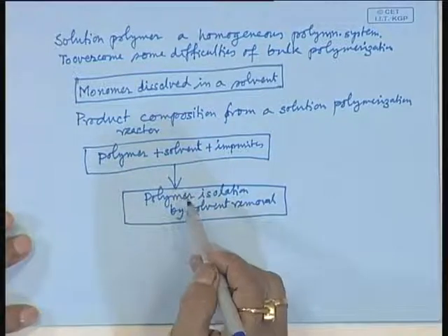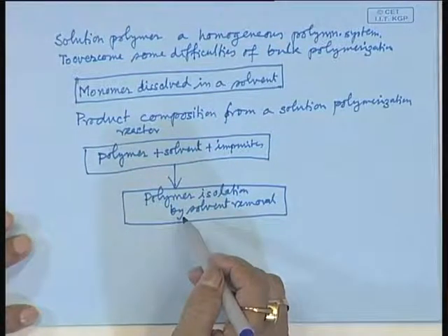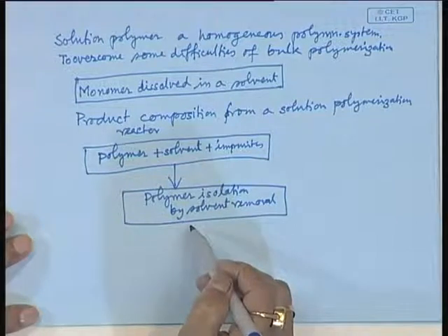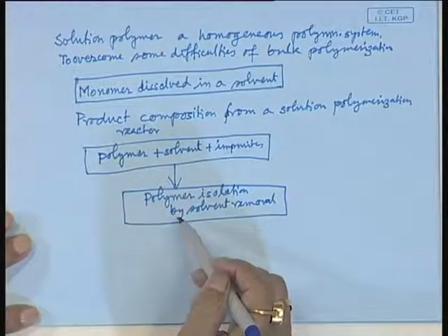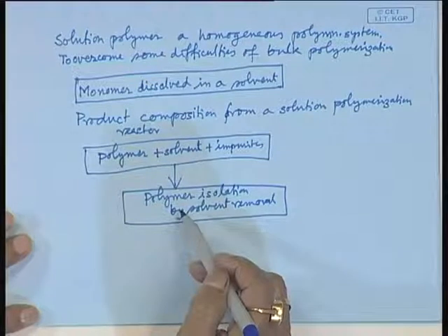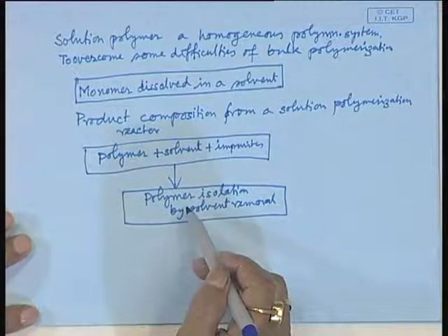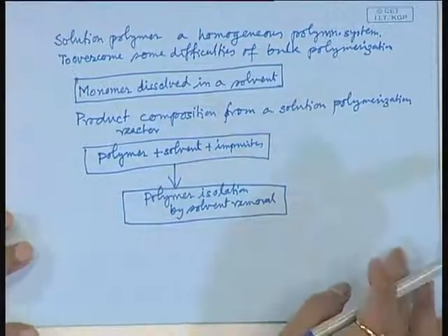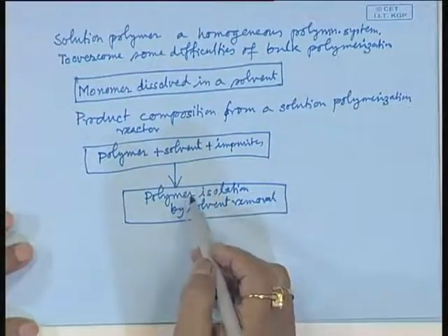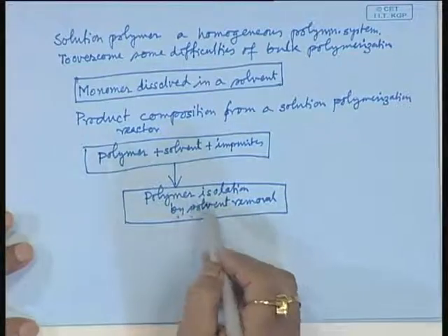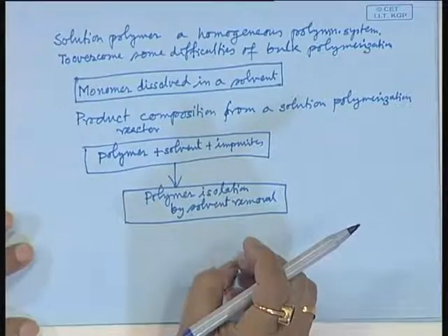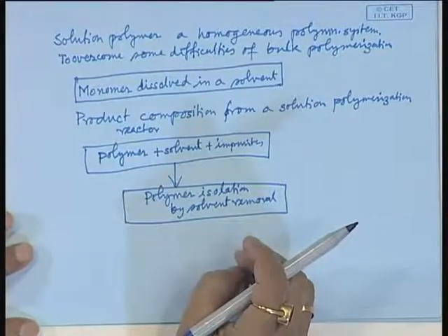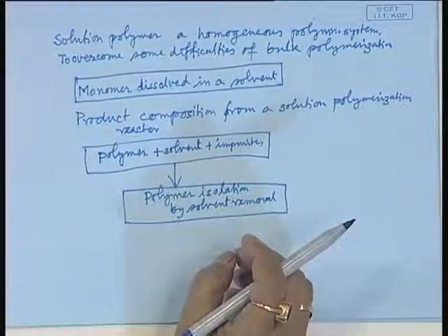Apart from that, it is not always possible to remove the last traces of solvent from a high viscosity solution, as more and more solvent is removed by distillation, stripping, and other techniques which are available. Being organic in nature, the polymer as well as the solvent, some solvent will remain trapped, dissolved in the polymer.